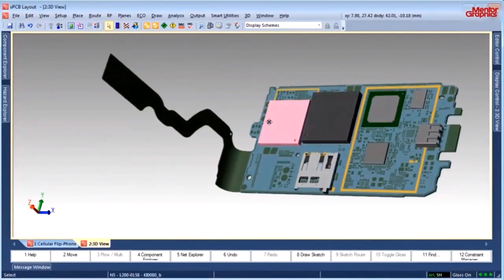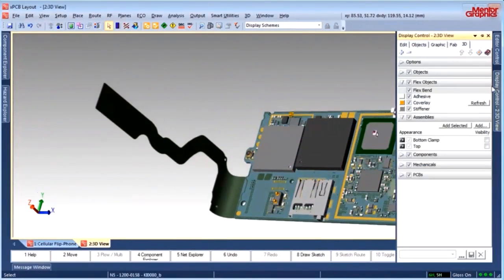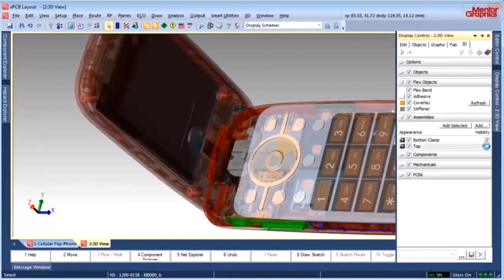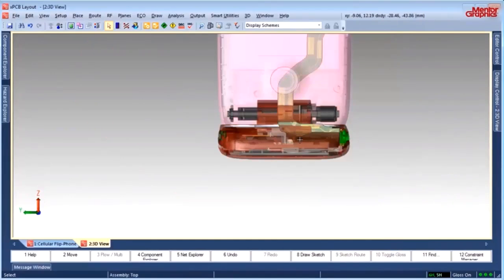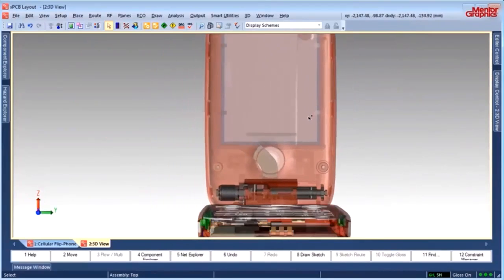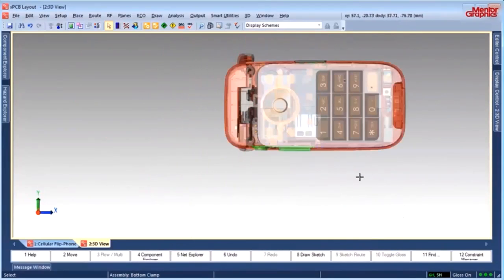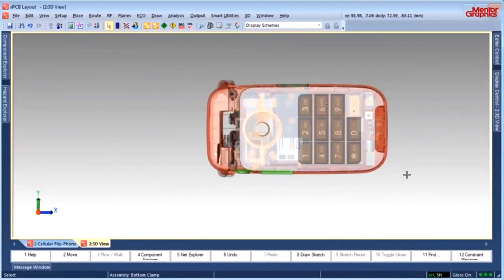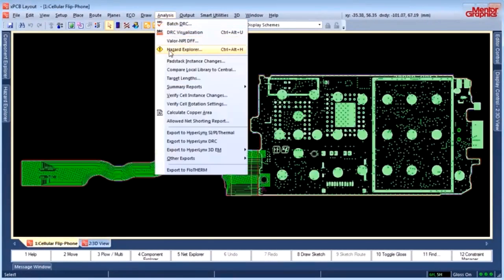Not only can you validate the design in Expedition, you can collaborate and exchange data with the mechanical engineer using STEP or ProStep format. Collaborating on bend areas, multiple outlines, multiple stack-ups, bend properties, and more ensures that all requirements in the ECAD and MCAD domains are met. Flex designs have critical design requirements that must be met in order to ensure quality of the overall design. Before the data is sent off to be fabricated, Expedition provides robust, updated design rule checks to identify critical issues.